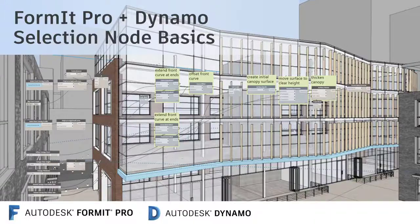Today I'll cover a workflow using FormIt Pro and Dynamo. With the 2021 FormIt release, we've added a selection node so you can drive Dynamo graphs by selecting geometry in FormIt. The 2021 release contains two sample graphs using selection nodes. One's called Railing Along Path and the other is called Array Along Path.